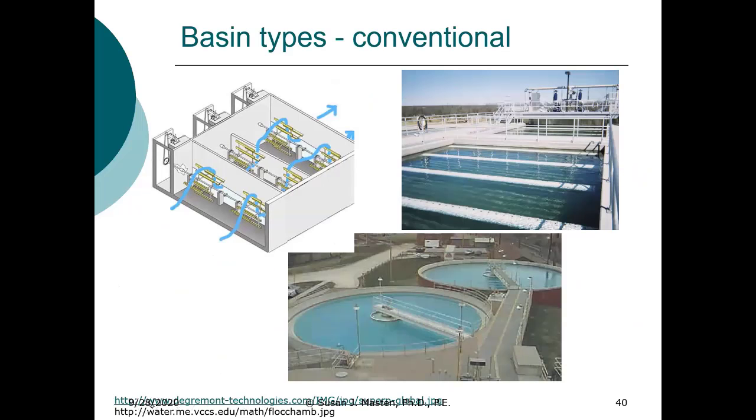I've just got a few photos to show you. We'll just look at a couple of basin types now that we've done all of the calculations for calculating our lime soda ash additions. So we've talked about paddle wheel flocculators. We can use these for flocculation. And you can see this is an open tank, and these, it's hard to see, but in here are the paddle wheel flocculators. And then you see the sedimentation basins.